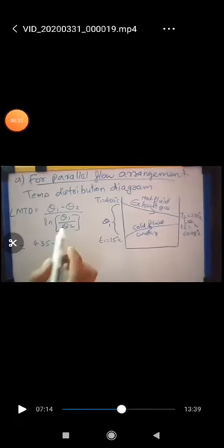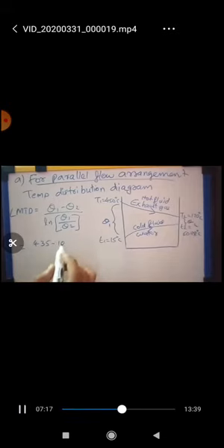Next we have to find out the value for LMTD, that is theta 1 minus theta 2 divided by ln of theta 1 by theta 2. Substituting the values we get 435 minus 109.02 divided by ln of 435 divided by 109.02. We get the value for LMTD for parallel flow arrangement as 235.6 degrees centigrade. That is the value for LMTD for a parallel flow arrangement.